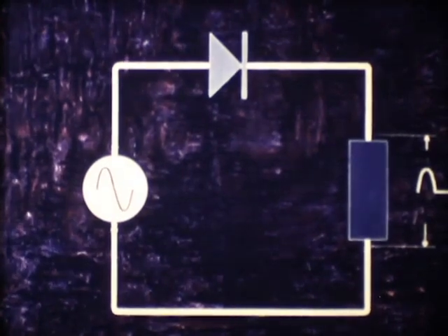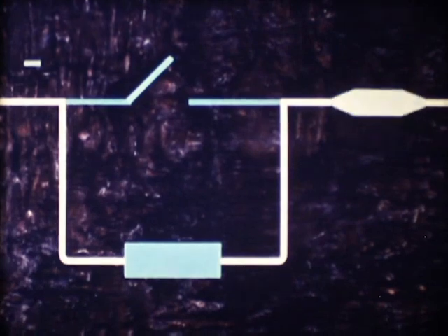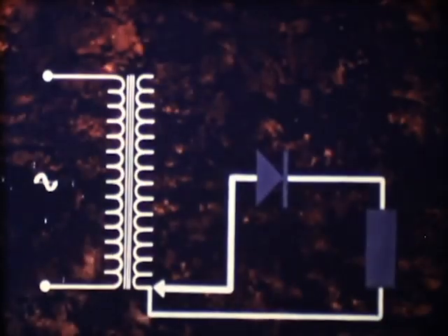The behavior of a diode can also be seen if, in its equivalent circuit, the junction is replaced by a switch. When the diode is forward biased, the switch is closed, thus short-circuiting the parallel resistance. The behavior of the diode is then determined purely by its series resistance. Reverse biasing of the diode is equivalent to opening the switch. As the series resistance is small compared to the parallel resistance, it may be neglected. Thus, the behavior of the diode is determined by the parallel resistance only.